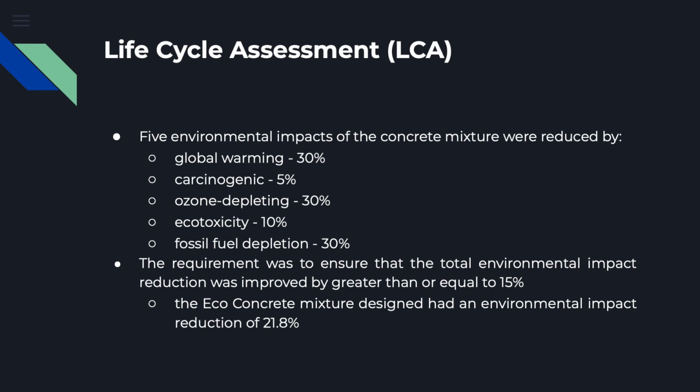The environmental impacts concerned with the EcoConcrete design include global warming, carcinogenic, ozone depleting, ecotoxicity, and fossil fuel depletion factors. The factors were reduced by 30, 5, 30, 10, and 30% respectively. The requirement was to improve by 15% or more. Our design improved by an average of 21.5%.